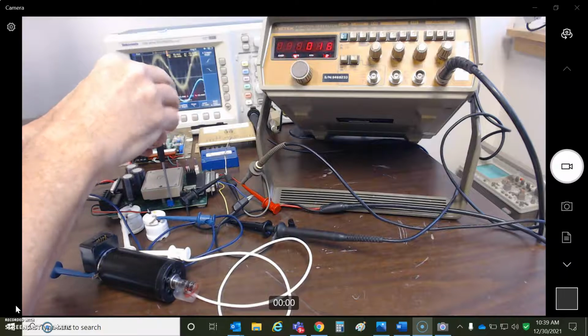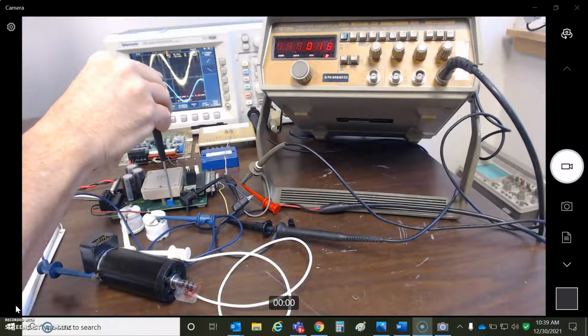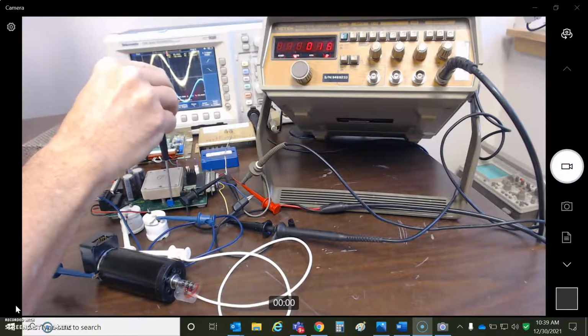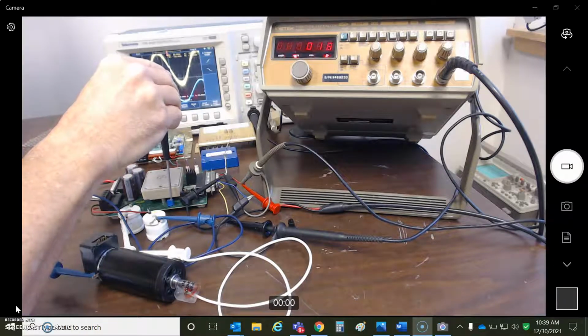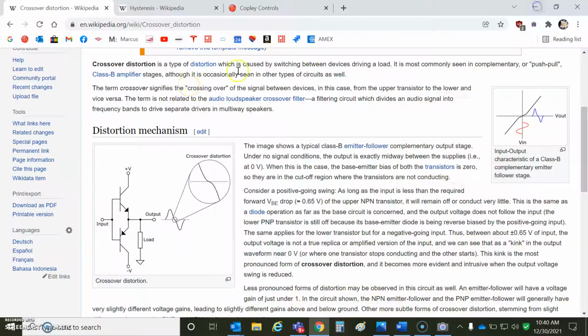But the idea of the crossover distortion is through 0, you're going to have a little bit of deadband in there. So when you optimally set it, it's not going to spin because of the inherent deadband. It's a form of hysteresis. So the hysteresis around 0 actually is beneficial for testing something in an open loop current mode. But of course, this is typically used in a system that measures position elsewhere and does some closed loop in some other controller. So a controller that closes the loop in just a dumb current mode drive.